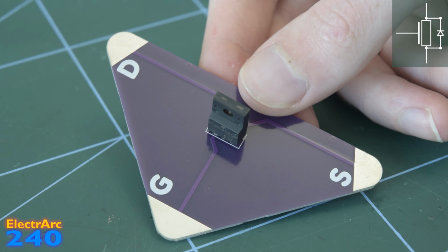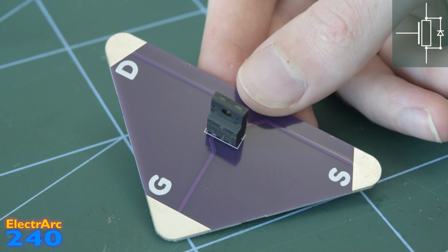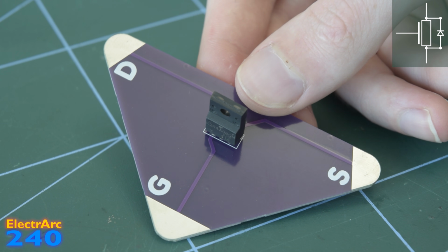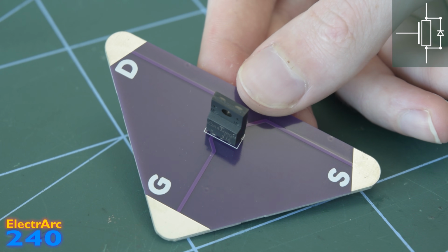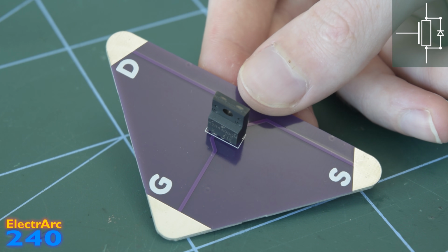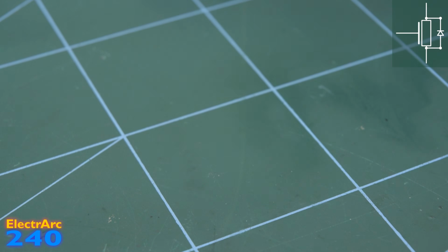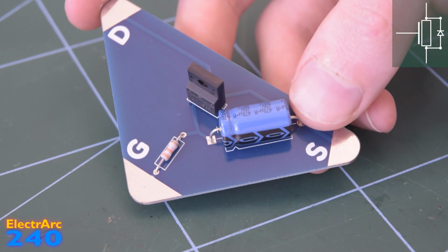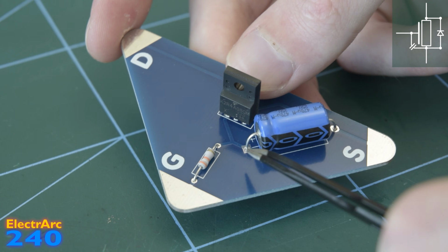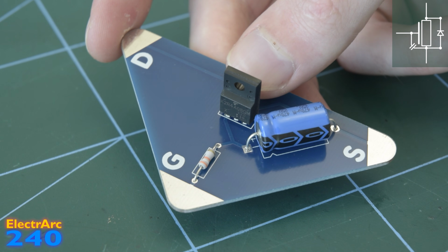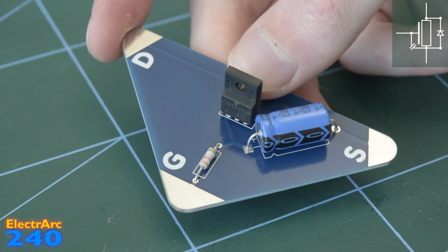Current? One of the key features of a MOSFET is that the gate requires zero current. While this may be true in steady state, so either off or on, transitioning between these states does actually require current. Why is that? Well, that's because between the gate and the source, there's actually a capacitance, so you have to imagine it like this. Here you can see a big capacitance between the gate and the source, and from now on we need to think of the gate as a